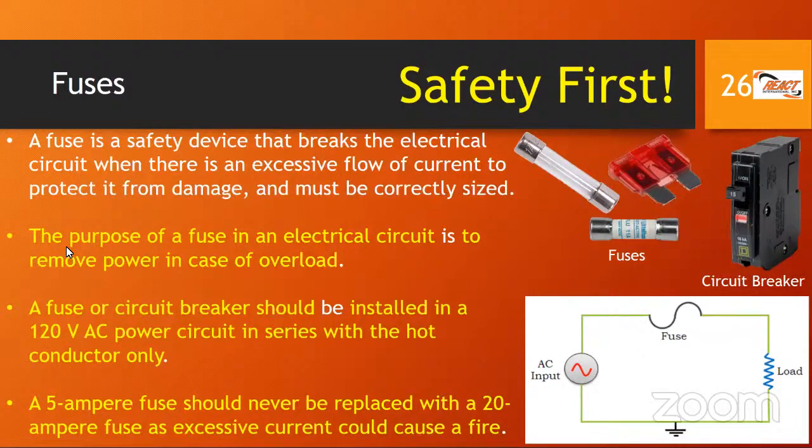But for the exam, we need to know that the purpose of a fuse in an electrical circuit is to remove power in case of overload. So in other words, if the current exceeds the value of the fuse, let's say it's a 2 amp fuse and the current goes to 2.5 amps, it will immediately extinguish or blow and allow that circuit to be disconnected so that no more current will flow. It protects, it's a protector, right?